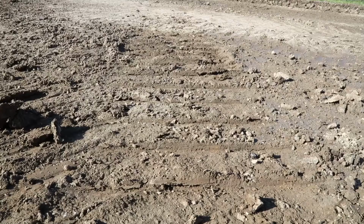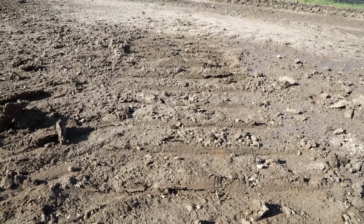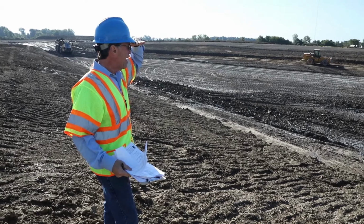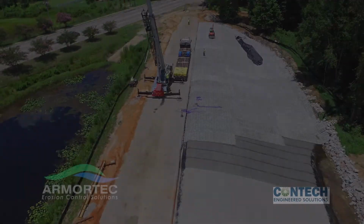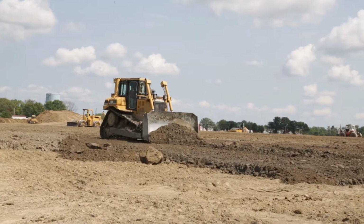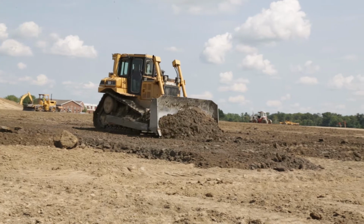How to maintain. Fill eroded areas to slightly above the original grade, then reseed, apply mulch, and anchor in place. How to inspect. Inspectors should check seeded slopes for rills and gullies. Surface stabilization is one of the most important principles of erosion and sediment control. Reducing erosion at the source is much more effective and efficient than trying to trap suspended sediment in surface water runoff.